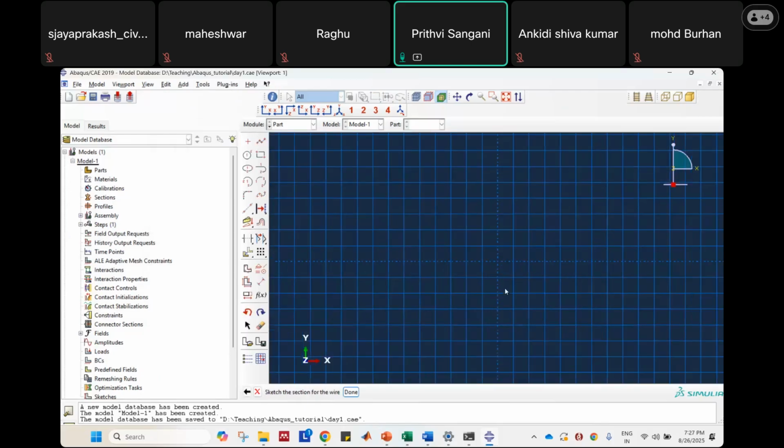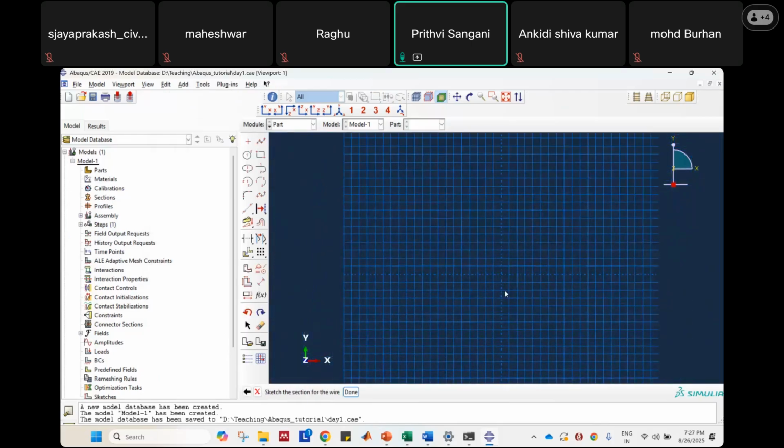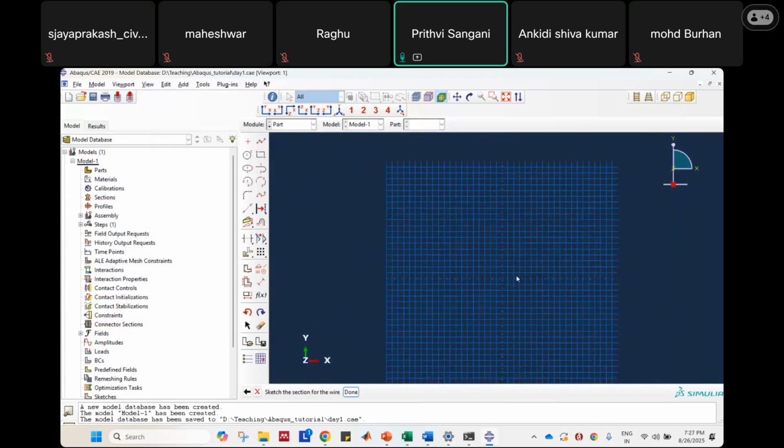Okay, now you will get this grid. I think you are able to recall your AutoCAD sessions, right? In AutoCAD, you also get something like this, grids and all. So this is again a sketching interface. Here you can sketch and create the geometry. If you remember, I gave something called 2000 over there. It's nothing but this grid is 2000 by 2000. If you have a bigger length, you give, say, 10,000 over there. That has nothing else to do over here. It's only that you want to work in a 2000 by 2000 kind of grid.